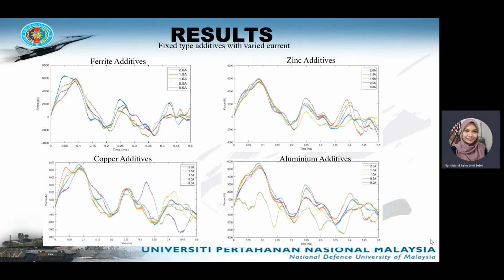This result also indicates that using magnetic particle additive will provide a better result compared to non-magnetic particle additive, because when the current is applied to the MRE device, the additive with magnetic particles will align to the current path like the anisotropic configuration of MRE and thus improve the properties of the MRE.